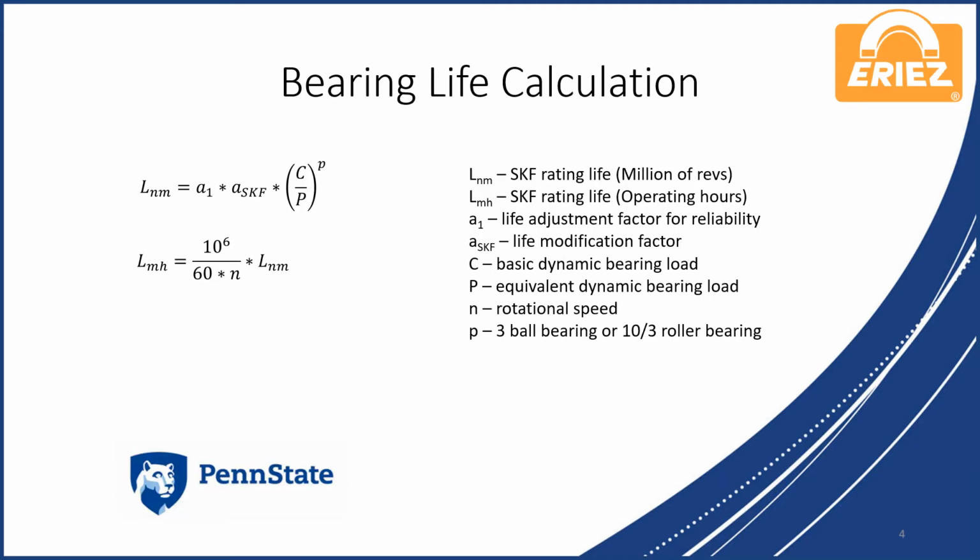Our next analysis is the bearing life calculation, where we did hand calculations as well as used the SKF software to determine the life of the bearings to ensure that they were above 60,000 hours as specified from Eriez.